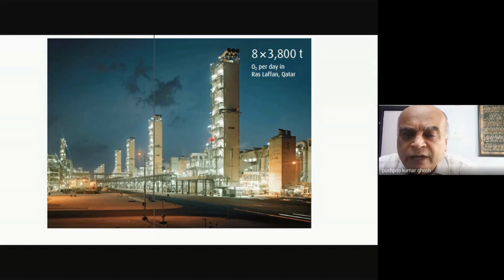So if your focus is only on standalone oxygen production, then of course the power requirement in the process would be much less, simply because you are utilizing the already cold and liquid form of discarded waste, the nitrogen, for doing the bulk of the cooling, and it's only the residual amount where you need to do the Joule-Thomson expansion, and obviously there's a lot of compression energy required for that.